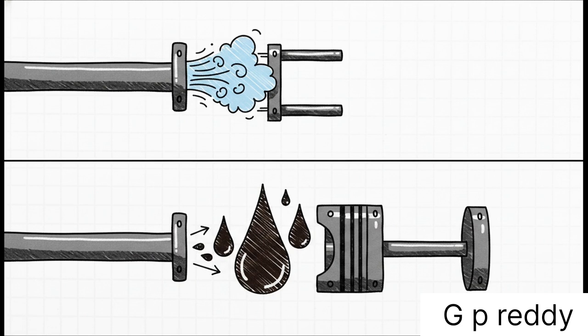First, we have pneumatic signals. I always find this one pretty fascinating because the machines are literally using pressurized air to talk to each other. The industry standard here is 3 to 15 psi of air pressure. If a valve needs to open, the controller quite literally blows compressed air down a tube to physically push it open. Then we have hydraulic signals. These take a much slicker, definitely heavier duty approach by transferring oil pressure through the system for just incredible raw power.